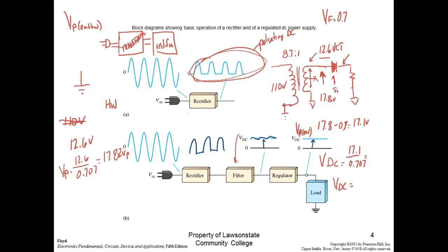So a regulator is an electronic circuit that maintains a constant output, or tries to maintain. There's no such thing as a perfect regulator. So you can go out there on your car, if your regulator's working okay, crank it up, put your voltmeter on there, and then start turning on your lights and your air conditioner. You'll see it maintains about exactly the same voltage because it's regulated, right? If your regulator goes out, I don't know if you've ever seen that before, people turn on their lights and they dim because the regulator's not regulating anymore.